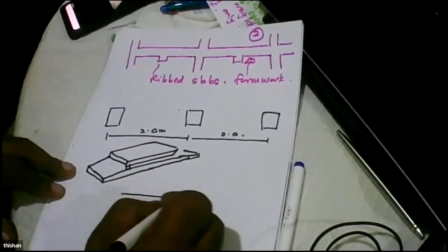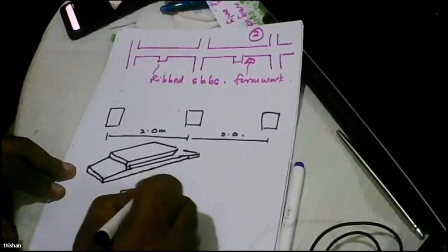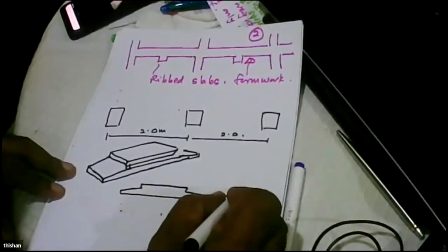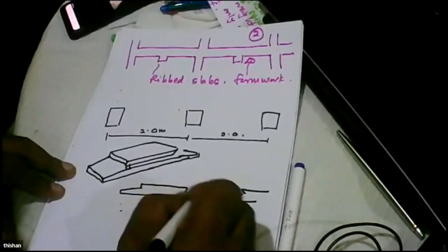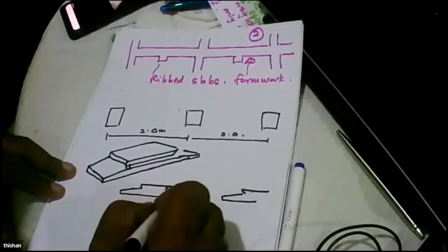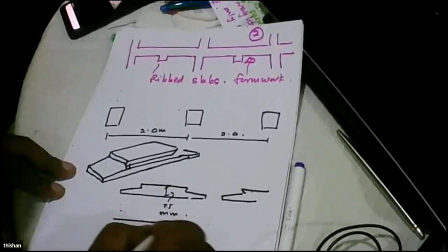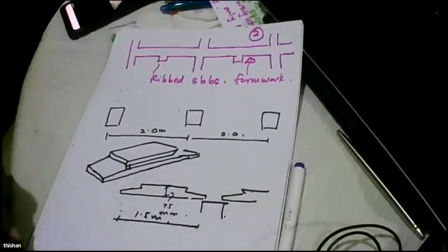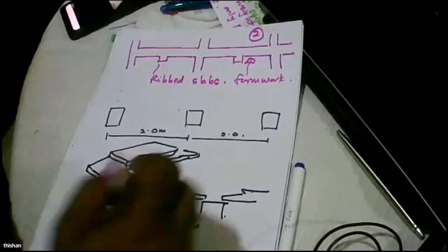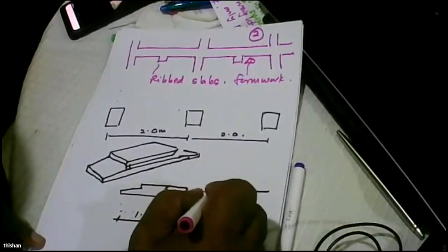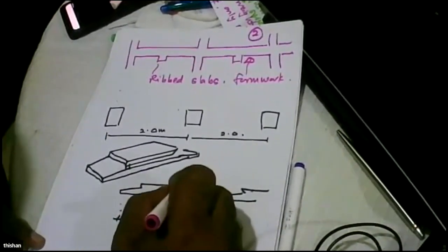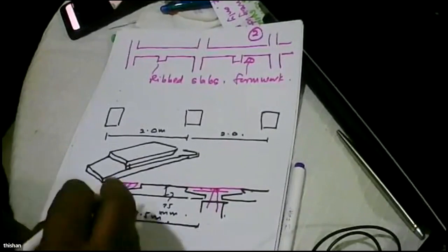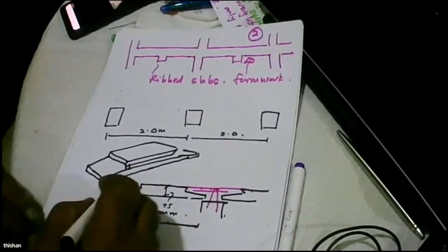The whole idea is we have a slab like that. The thickness is 75 millimeters here, spanning 1.5 meters, supported on a beam. Then we are supposed to add some reinforcement, link it up, and fill this gap. So the final product is only 75 millimeters of thickness.